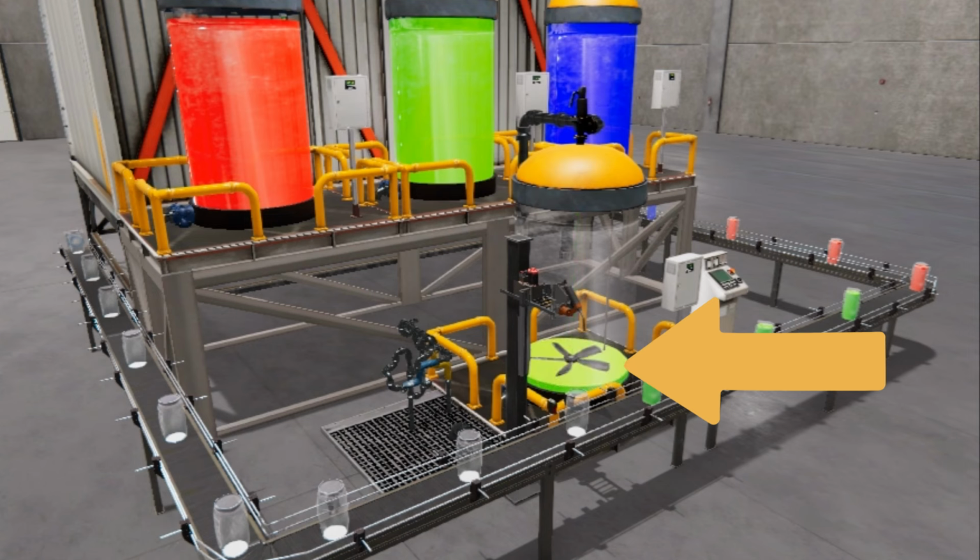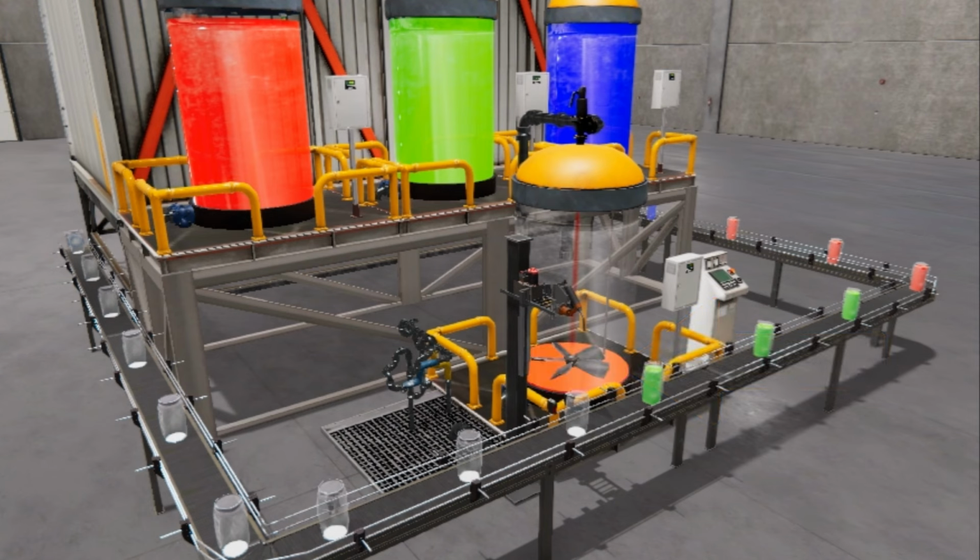Once the volume reaches 1000, we will turn off the mixing tank input and energize the output. Once the mixing tank volume returns to 0, the purge is over. The mixing tank bottom turns white to indicate we are ready for the next recipe and bottle number selection.